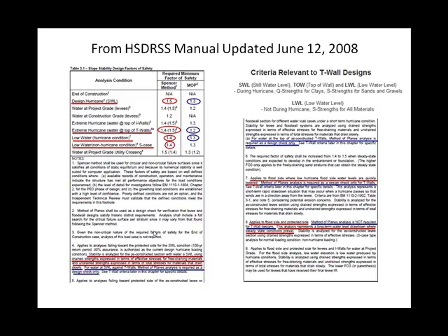But for the still water condition, we assume that the strengths that we're going to use for clays are going to be the Q strengths, or the undrained strengths, and the strengths used for the granular materials are going to be the drained strengths. The still water level is established by a hydraulic engineer and given to the geotechnical engineer for the design. The top of wall is self-explanatory. That's for flood water at the top of the wall. And the low water level condition during a hurricane is also given by a hydraulic engineer to the geotechnical engineer.